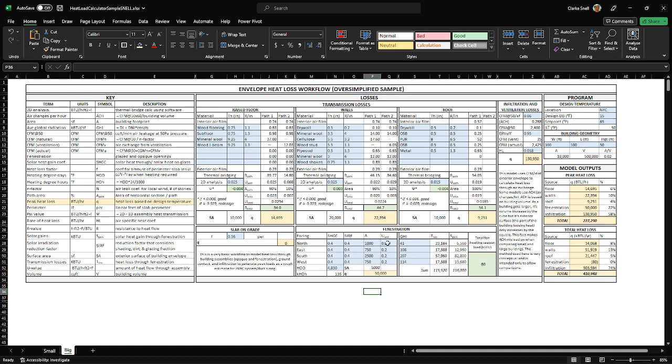Then we have the area and the U value per unit. That's based on what we choose. And then we have the global horizontal irradiance, which is how much sun is hitting our window. And then we have total heat loss and then solar gain, because we have loss through the glass, but we're also gaining heat with the sun coming in. And then we get a total fenestration heating season load, because right now this delta 50 is for the heating season. Okay, but the point is we put all those things together.